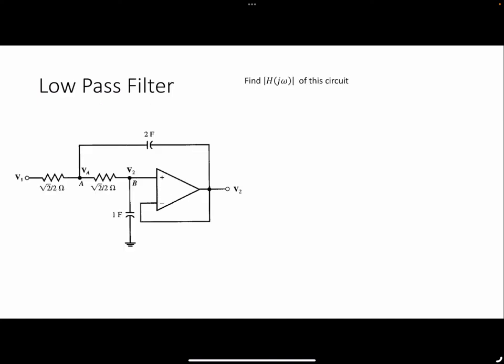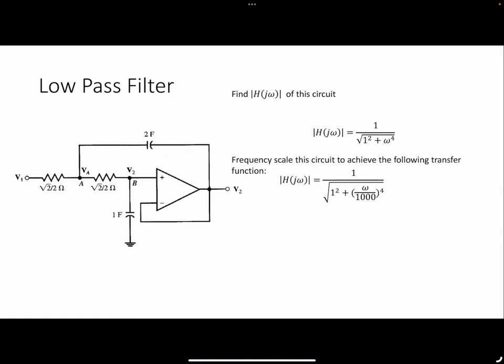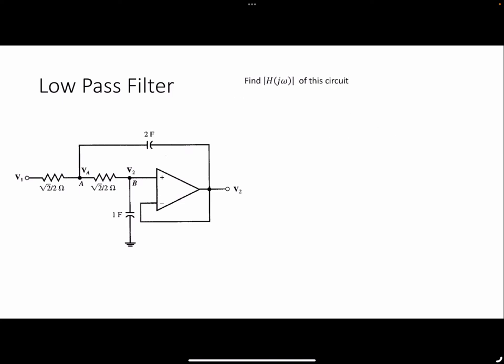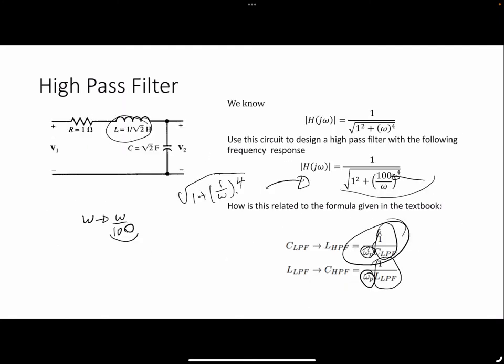Yeah, so there's nothing more. So is the omega p in those formulas basically just a factor of frequency scaling? It's something that we inherit because when we designed this, we chose omega p over omega as a transformation factor. So we took all of our designs and frequency scaled them by omega p. And so on the way back, we have to divide by it, or remove it from our frequency scaling.